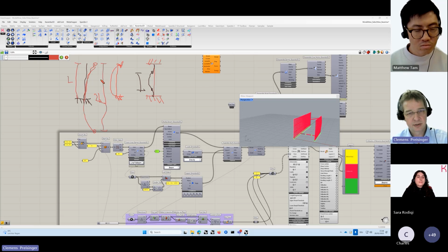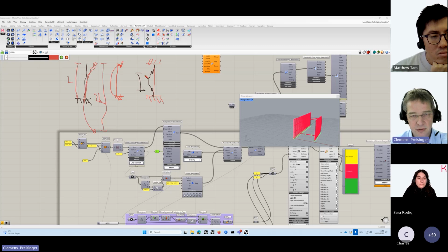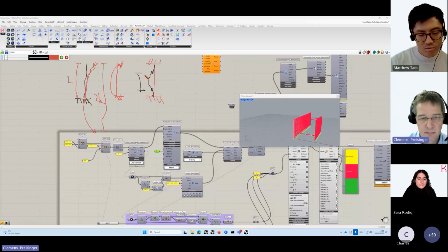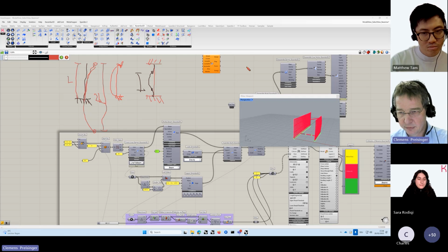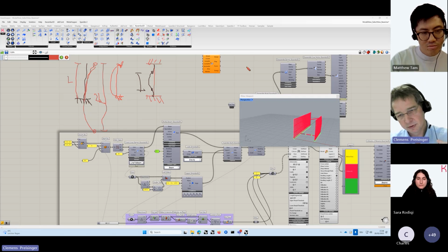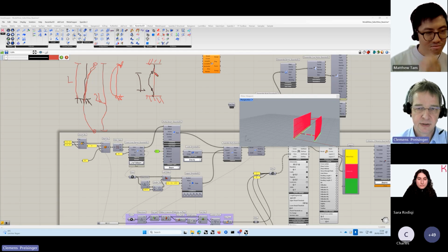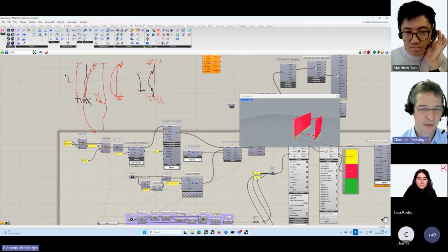And in a real structure, since you normally do not have a real hinge somewhere, but only maybe a connection which has a certain spring stiffness, it's not easy. But in that case, you could use the Karamba buckling component to see what the buckling shapes are, and then from those buckling shapes you could determine the approximate distance of these zero moment points. Okay, yeah.